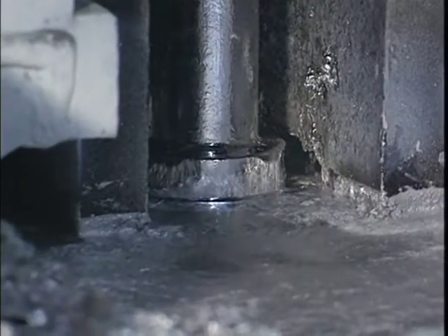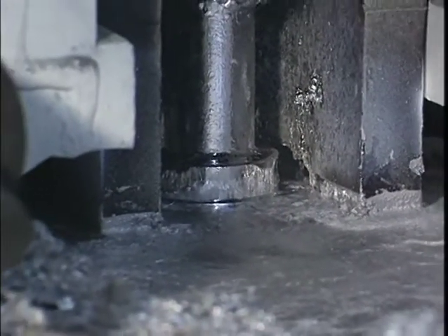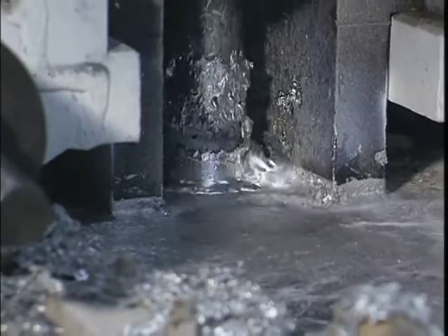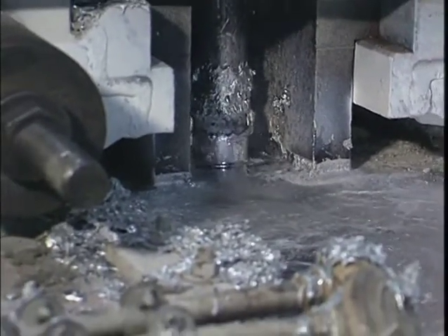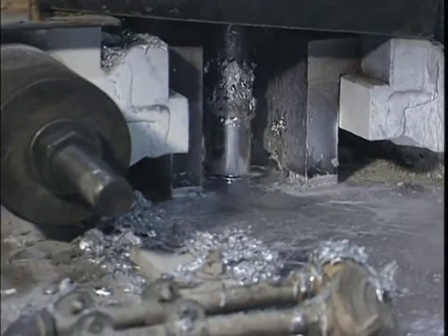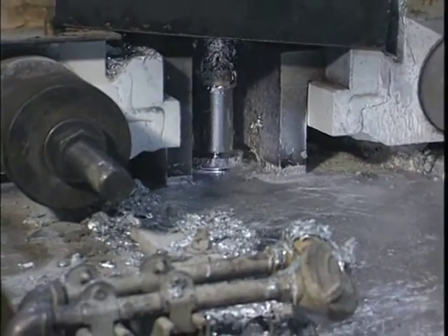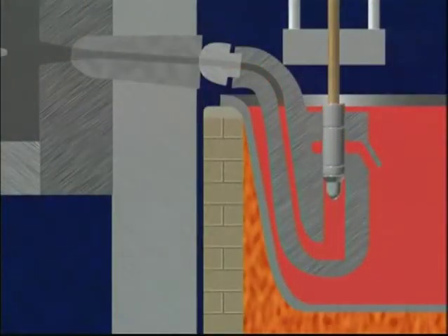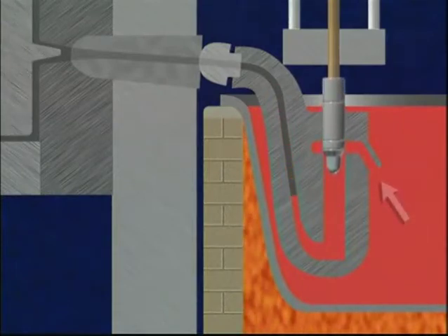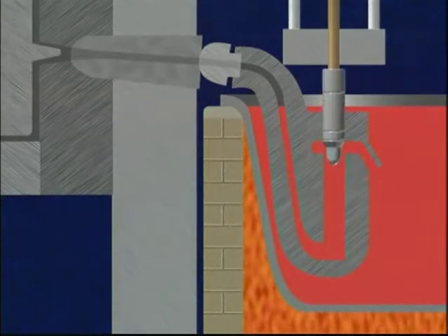The plunger end of the injection system and the lower portion of the transfer pipe are submerged in the molten metal. For this reason, aluminum and copper alloys are unsuitable for use, since they chemically attack or erode the submerged injection system. When the plunger rises, a charge of metal enters the pipe through a port.